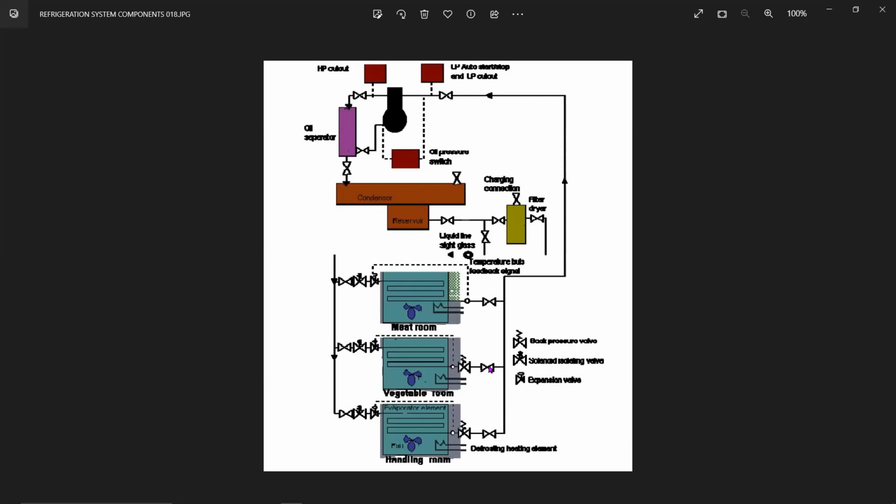तो वहां पे बैक प्रेशर वाल्व की जगह पे एक कैपिलरी ट्यूब दे दिया है, very thin tube, and that is basically creating the back pressure. ठीक है, as the outlet goes it is going to keep the pressure in the line; it is basically going to throttle the outlet. ठीक है, मतलब ऑरिफिस तो नहीं है उसका, but the line is very small. ठीक है, जैसा हमने देखा था ना कि थर्मोस्टेट एक्सपेंशन वाल्व के अंदर भी कैपिलरी ट्यूब डिजाइन दिया हुआ है. ठीक है, similarly here also there is a fixed orifice over there and there is a thin tube after it. तो वो भी वही काम करेगा. So that will always give a pressure difference over here.